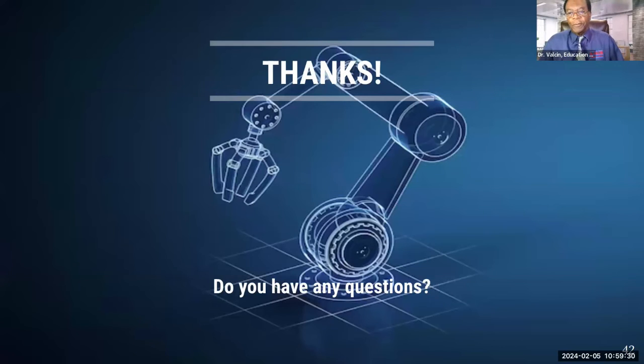ROS 2 provides some software tools called quality of service, and with quality of service you define whatever you want. I can define reliable, I can define best effort. What does this mean? It means I am telling my publisher, or my subscriber, how to handle the messages.